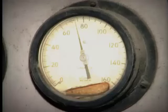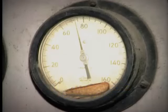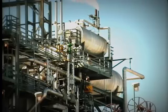The pressure inside the de-aerator varies with the extraction steam pressure. At full load, this is likely to be, say, 150 psi. However, at lower load, this pressure would be considerably lower. Often, the de-aerator is located at a high elevation in order to provide a positive pressure to the suction of the boiler feed water pump.